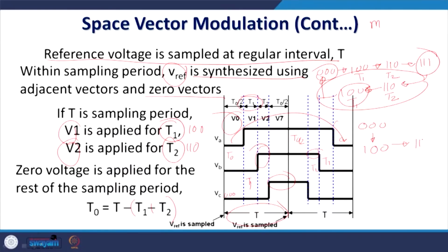So, it is 1 1 0, thereafter 1 0 0, thereafter 1 1 0, thereafter 1 1 1. In that way you can reduce the switching losses by this technique, and also you can control the duration of it. I shall come to that later. So, how much duration it will be turning on and all. Thus you can have control, which is required for minimizing the losses.